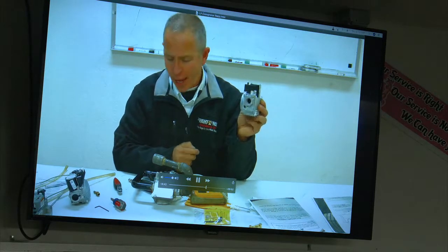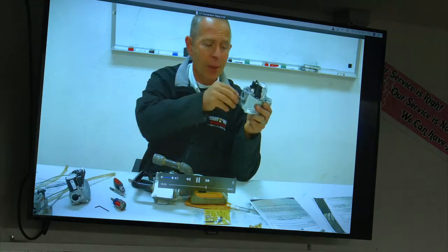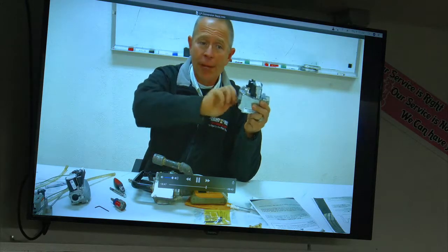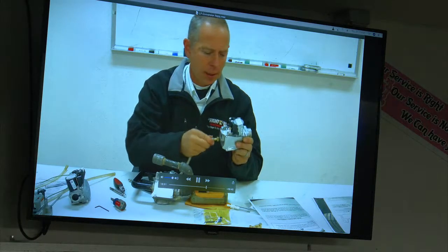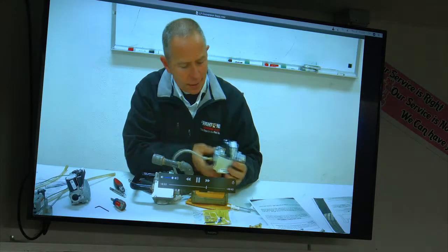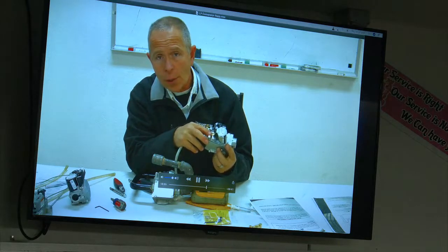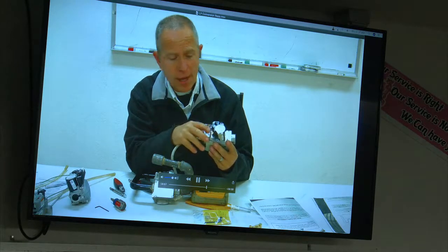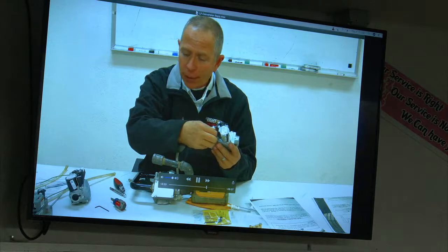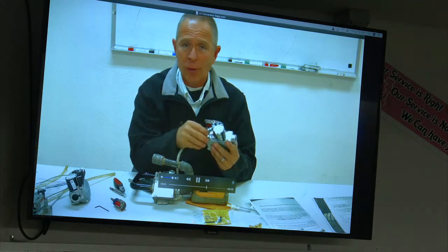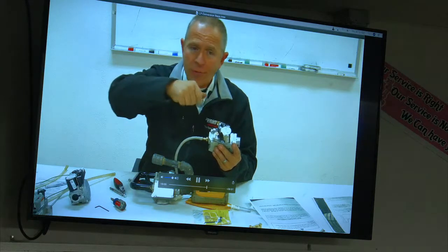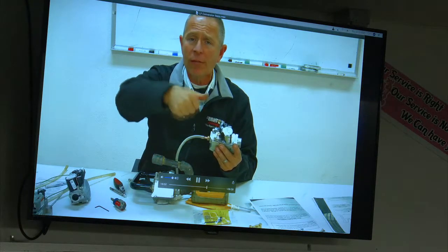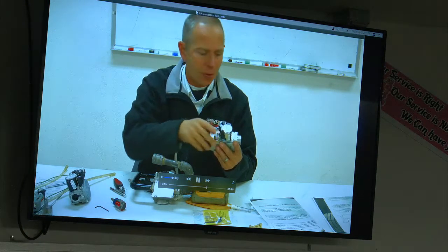So then we're going to do the manifold side, and the same thing's going to happen. We're going to put our barb fitting in, make sure it's nice and snug, connect it up, and then we're going to set. This is a single stage, so we only will set just that one stage. We'll take the cap off, and then adjust that set screw, which makes the spring go up or down inside there. As you screw it in and down, the pressure increases. As you screw it out, the pressure decreases.